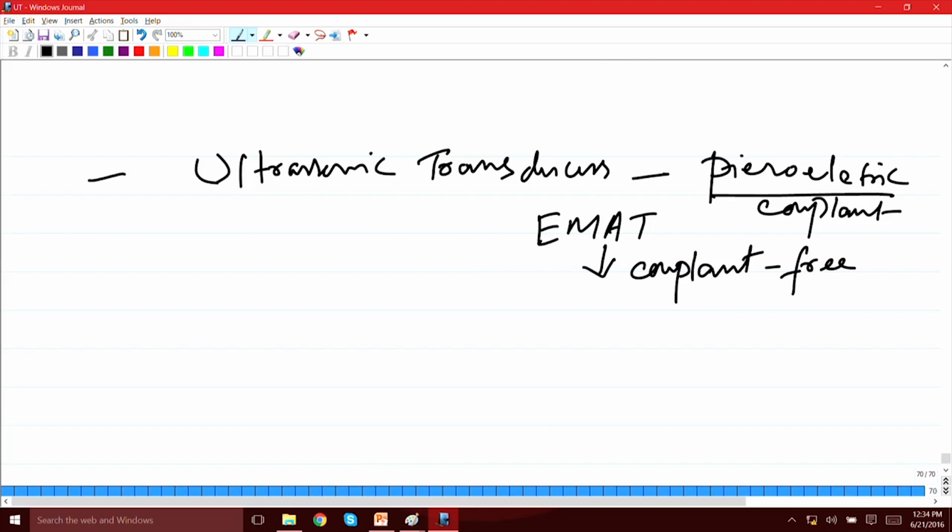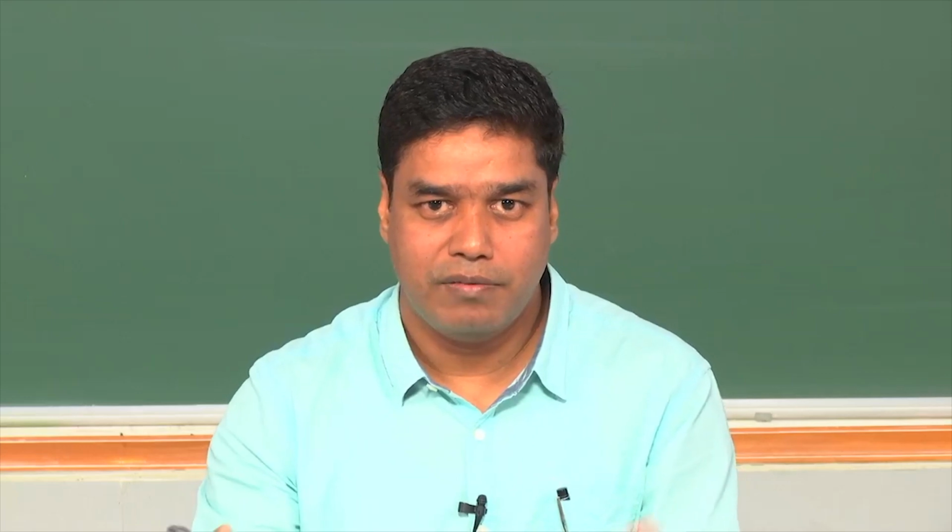Okay. Before that we also learned about the beam shape, which depends on this particular ratio lambda by d, wherein lambda is the wavelength of the sound waves and d is the size of the transducer. And then we saw that for all practical cases wherein d is much larger than lambda, the beam becomes directional and takes up a shape which resembles kind of a searchlight.